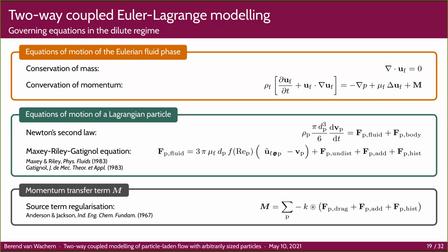No, I think you can actually say that these errors are bad for the motion of the individual particles, which you might not care so much about, but they're also bad for the macroscopic properties. Because for instance, your pressure drop over your fluidized bed will balance the forces on the particle. So if you look at the Ergun equation, for instance, that's exactly what you do. You have a fluid pressure which counters the gravity force on the individual particles. So if you get your drag force 10% wrong, you're going to get a 10% error in your pressure drop over your total fluidized bed. Okay, but you expect the error to stay of the same order of magnitude, not that it blows up, or that things are averaging out at some point? I think you're making similar errors at each individual particle. Yes, so it does accumulate. Okay, Chris has a question.